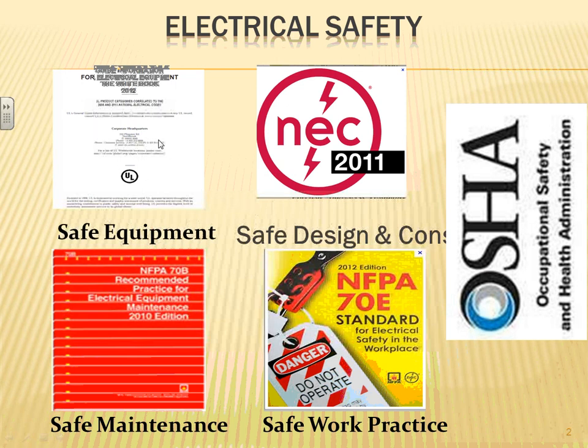So that's the safety of the equipment. It has to be UL listed. Then we have safe equipment. We install and design it based on the 2011 NEC code book. Then we work on it energized based on 70E so we can go home safe. We don't blow up our hands or electrocute ourselves. And then I don't know how many of you guys know the NFPA 70B. 70B, if you do any maintenance or you write a report for people to do maintenance, this is the Bible of maintaining any power system. And we all know, guys, the power system is only as good as the maintenance program that you have.